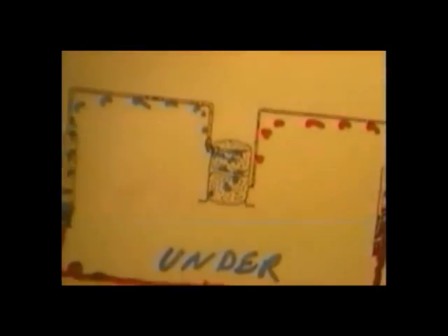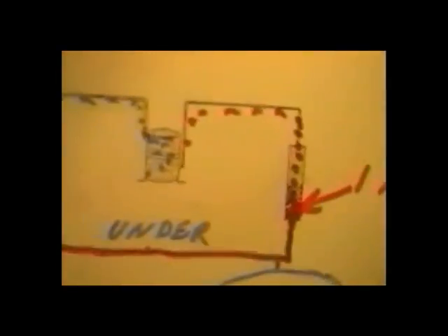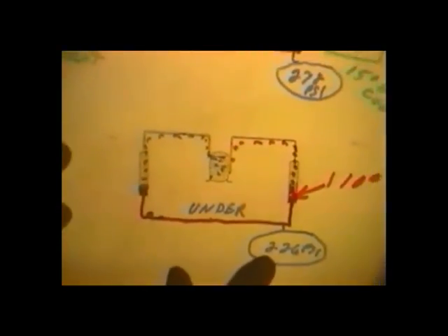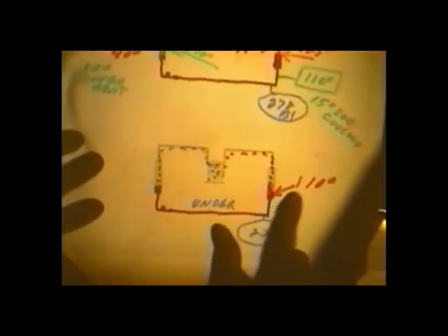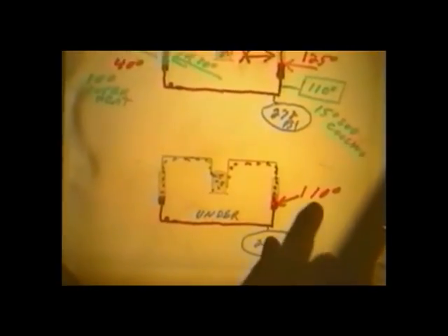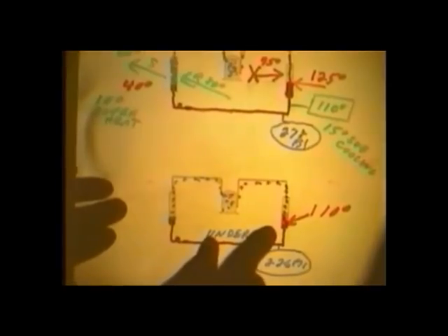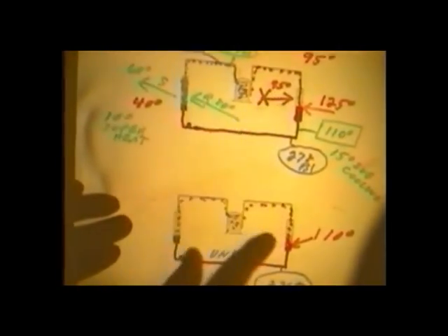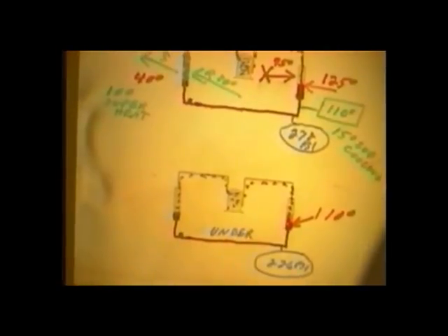So what I'm saying, Herb, is that we undercharge it. It's undercharged for whatever reason: technician, leak, or something. Right now it's undercharged. I put my high side pressure gauge on, I read 226. I know that my saturation temperature is right there, 110 degrees. Isn't it true that I got more vapor and less liquid now? Over here was normal. Now I got more vapor, less liquid.